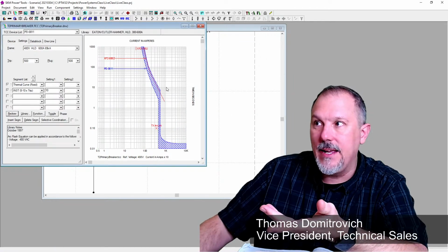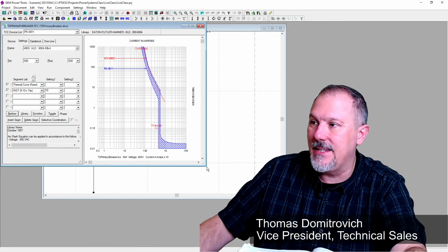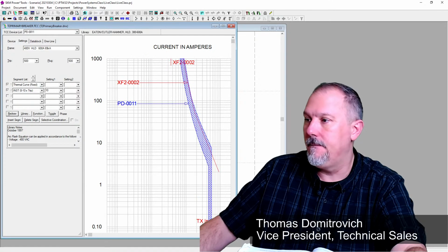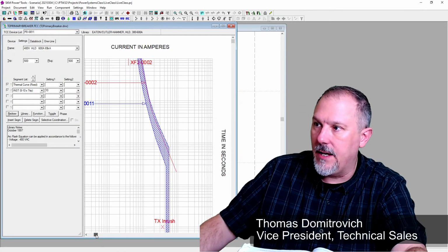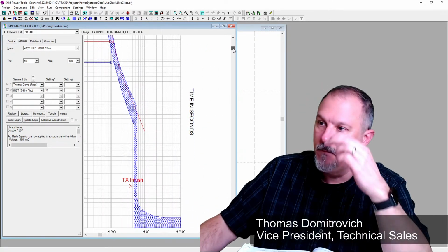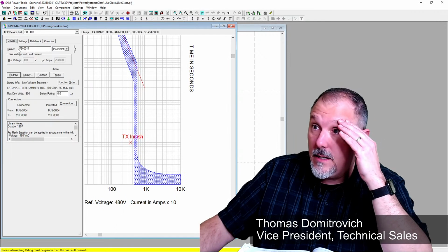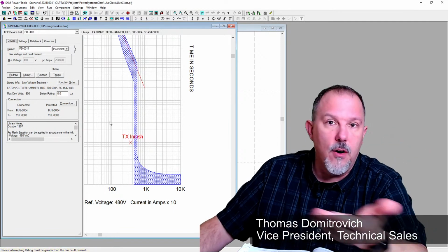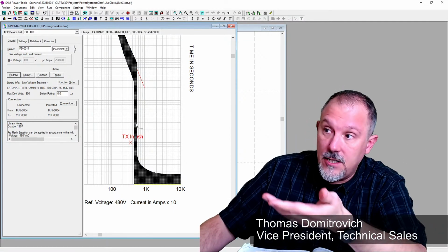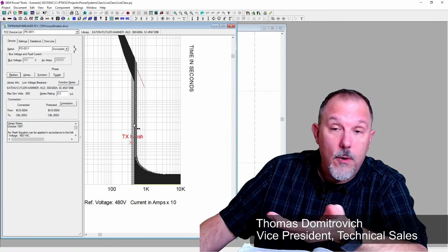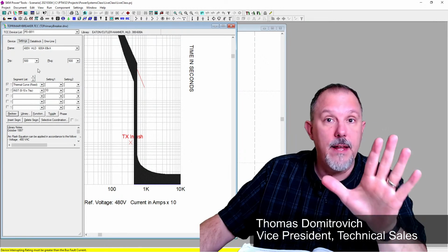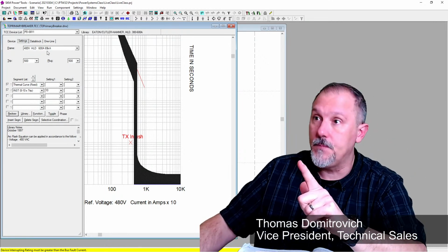And look at where my inrush, my instantaneous is. So this is a thermomagnetic circuit breaker. It is a Cutler Hammer Eaton HLD breaker, so it's an L frame breaker. I can adjust the instantaneous down if I wanted to, but it is a 500 amp. So I did go with a 500 amp breaker.